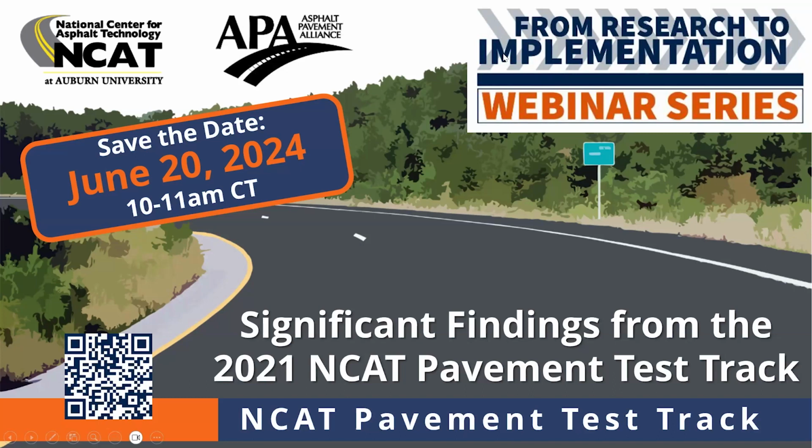So with the middle-up fatigue cracking that we see from that debonding, I love that set of slides that you guys have with the 6 sets, where you can see the layers debond, and then the crack begins to propagate from the middle of the pavement section upward, and then propagates down again because we didn't get the proper tack coat in there. But with that type of failure on a lower volume road, do you notice a difference in the crack pattern, or does it follow those same rules of thumb that you discussed?